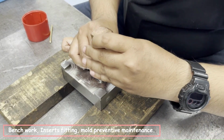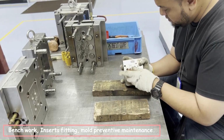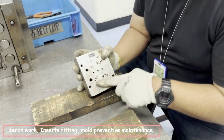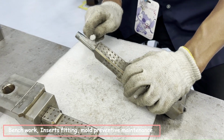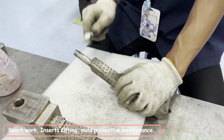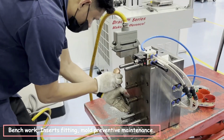Preventive maintenance for molds is essential to ensure their longevity, reliability, and consistent performance in the injection molding process. After each production run, remove plastic residue, dust, and any foreign materials from the mold. Use soft brushes and compressed air to clear out any hard-to-reach areas.